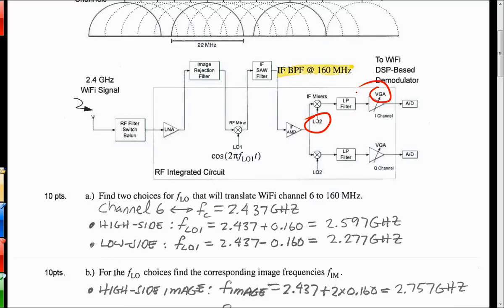You get lots of quantization error. So the VGA can be used to keep the signal dynamic range as closely matched to the converter's dynamic range. If you've never thought about that, it's something that you may bump into someday. It's not magic. Your analog doesn't become digital as perfectly as you'd think without having some means of matching the dynamic ranges up.